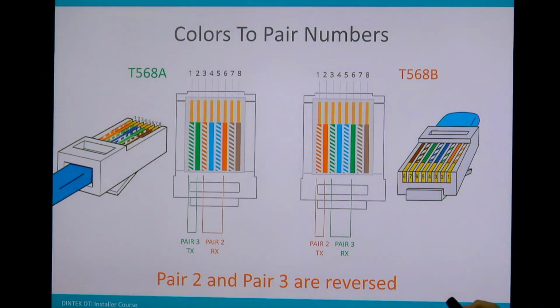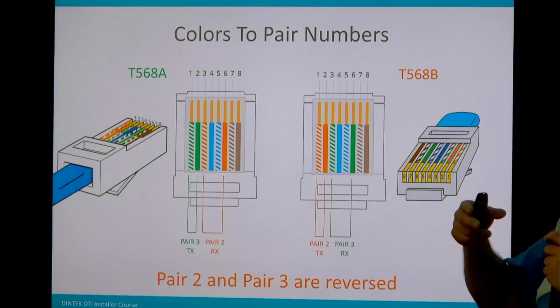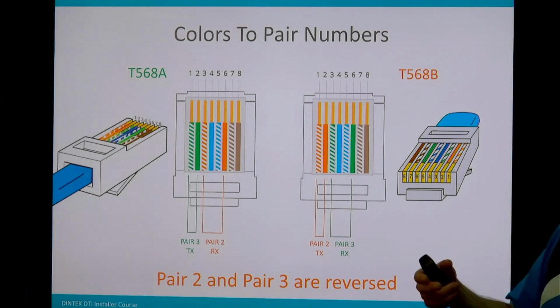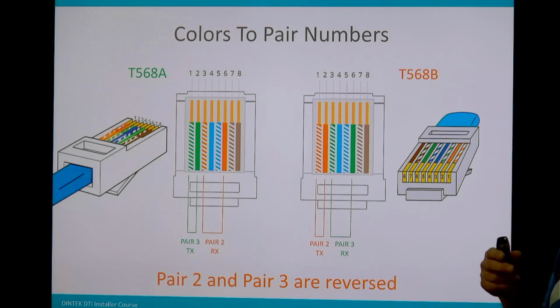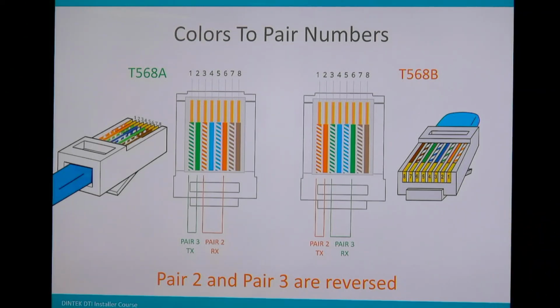Is there an advantage of using one? Not particularly. It really doesn't make a difference. It's a personal preference. But of course, we stick with the predominant cabling spec for that country, because otherwise you might have somebody fitting off the patch panel and somebody else fitting off the jacks, and they're both doing different specs, and then you're going to run into problems. So we keep the one type.